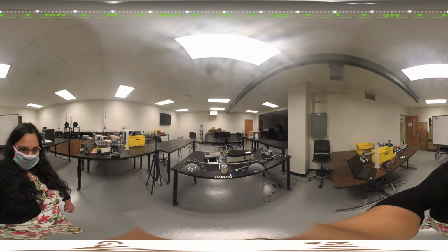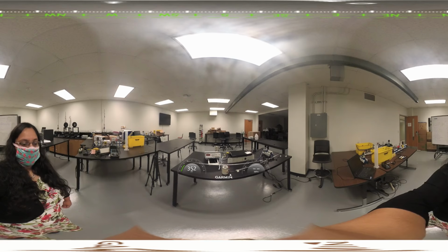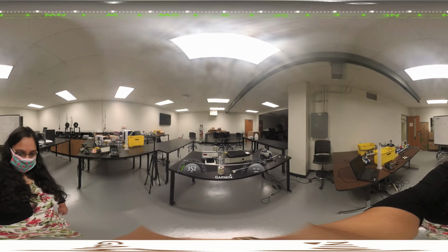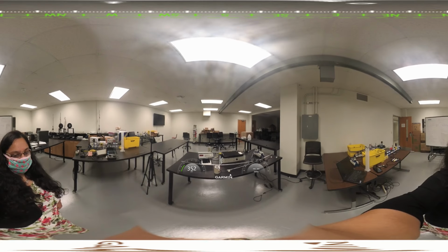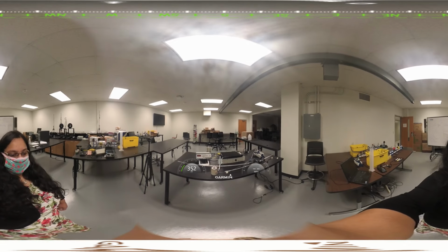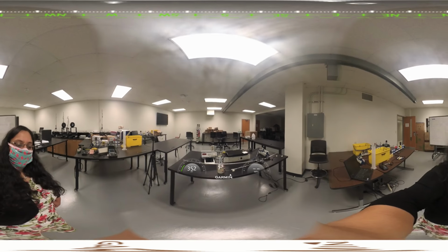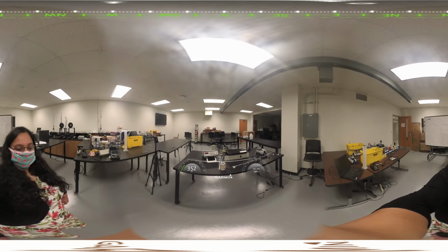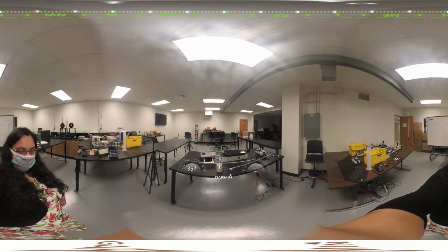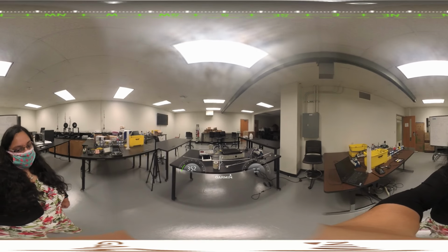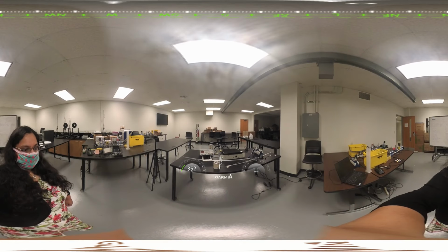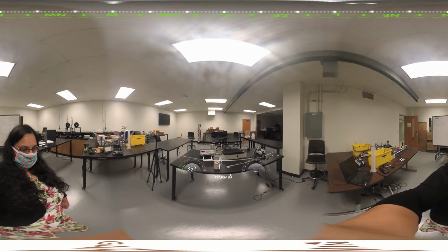Moving on to the second lab, the lab is going to be the vibration lab. In this vibration lab, you are going to study a hypothesis whether the beam that you see here behaves as a cantilever beam or a free beam. The properties are given to you, and you're going to compare the numerical or theoretical calculations with what you see in this experiment. And you're going to infer if it is a free beam or a cantilever beam by exciting it to different frequencies.